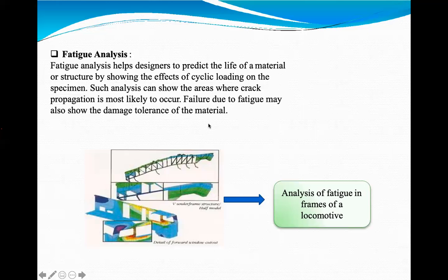and we say that our equipment or product is safe, and in reality it fails after a certain time, we will be wondering why it failed. So whenever we have cyclic loading, our structure or equipment may fail much below the yield stress or yield strength.